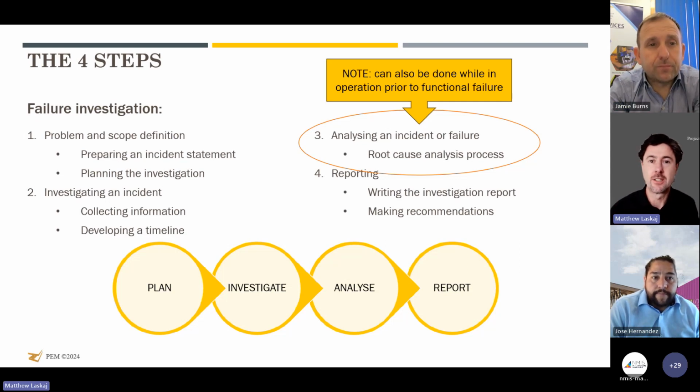Everyone jumps to technology as their first solution, but it doesn't have to be technology. I know we're going to talk about technology with some of your videos because they look better than interviewing a fitter, perhaps. But the operators and the technicians in the field, we can get so much information and useful knowledge out of them. As a reliability engineer working in the refineries, I used to spend all my days just walking around talking to the people, saying, what are you noticing? Oh, that's making a noise. Ah, that always makes a noise, don't worry about that one. But if that one makes a noise, that's when we start to worry. So gathering that baseline is really important.